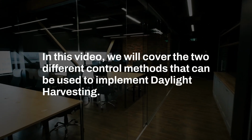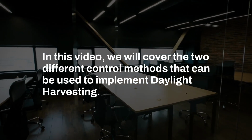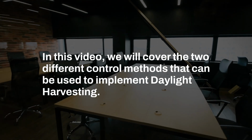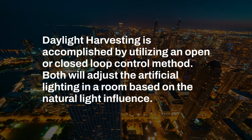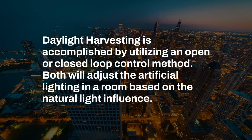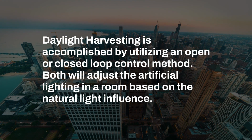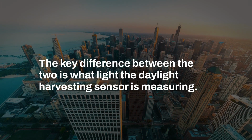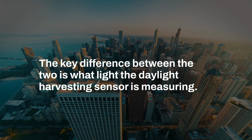In the previous video, we reviewed the goal and function of daylight harvesting, and in this video, we will cover the two different control methods that can be used to implement daylight harvesting. Daylight harvesting can be accomplished by utilizing an open-loop control system or a closed-loop control system. Both will adjust the artificial lighting in a room based on the natural light influence, but the key difference between the two is what light the daylight harvesting sensor is actually measuring.